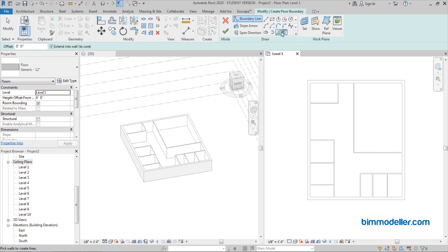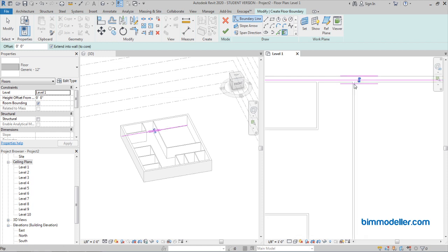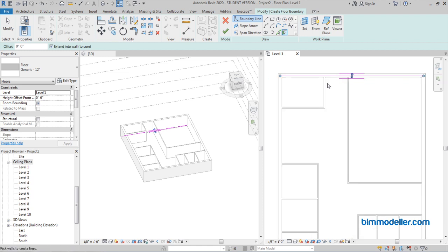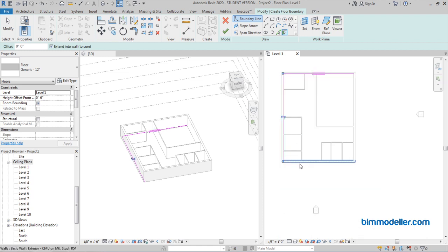Let us select the wall, pick walls. You will be able to pick the walls, and it will select your interior edge or the exterior edge. So we have to create it till the exterior edge. If you want, you can flip it to the other side, or flip it inside. Let us make that an edge and select the other edges like this, or you can pick your line edges wherever you need. And I wanted to pick the edges like this.